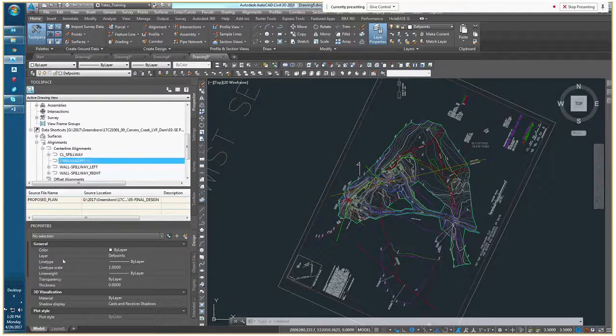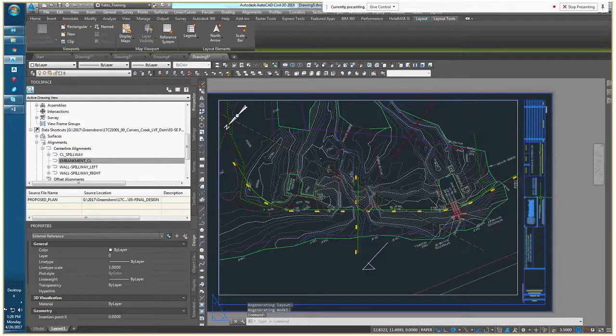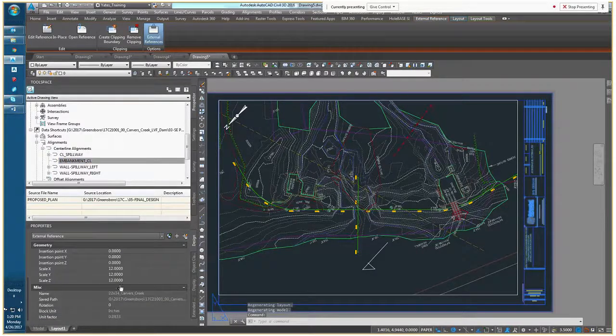So when we looked at scaling this title block by 12, I just want y'all to remember, if you do have to scale something by 12, never ever use the decimal equivalent of 1/12, because there is no decimal equivalent. You could carry it out forever and ever and never get to the decimal equivalent of 1/12.